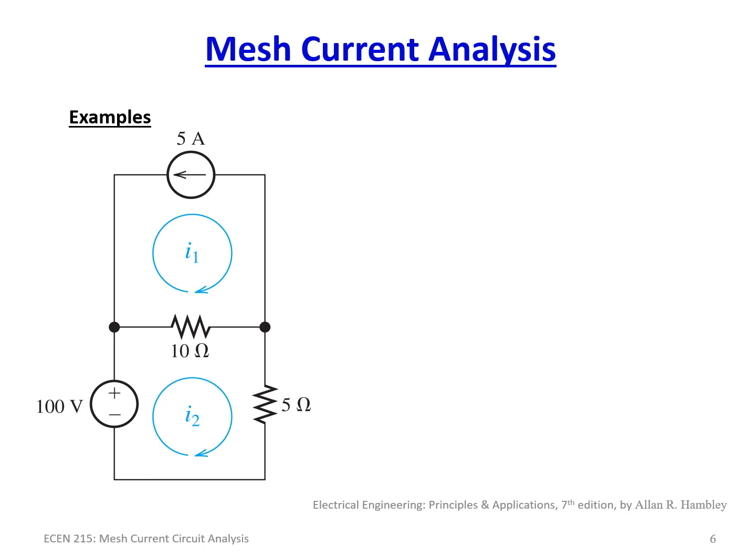All right, what about this one? So here we've got, again, two mesh networks. So we can do the exact same thing. Here, actually, we know something immediately off the bat. What is the value of I1? It's minus 5 amps. Okay, why? Because we're given that. This current is defined as going this way. In other words, I1 is that. Well, I1 has been defined, so we know I1 is equal to minus 5 amps. That is a known.